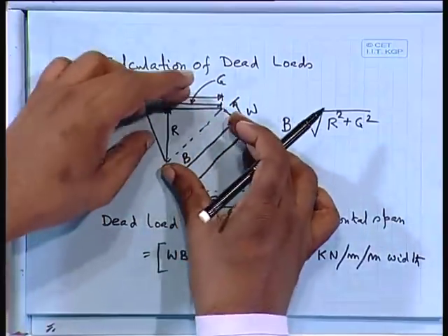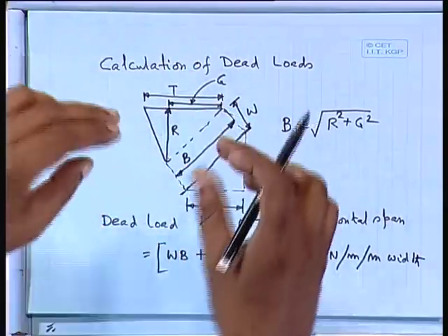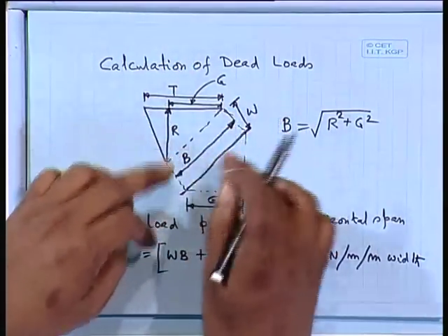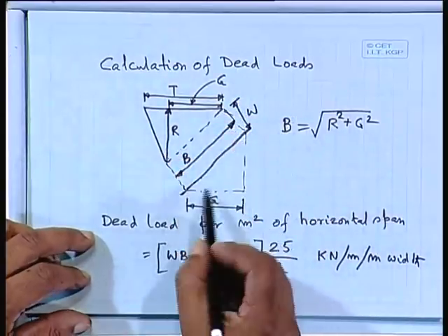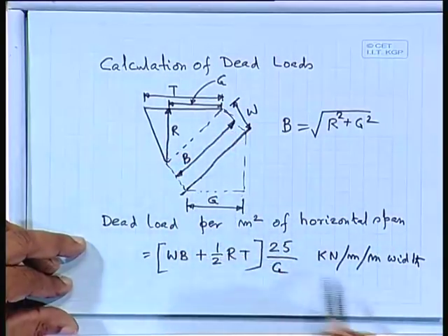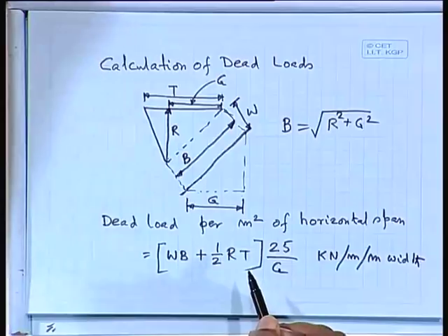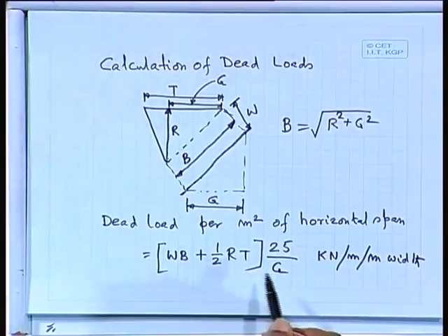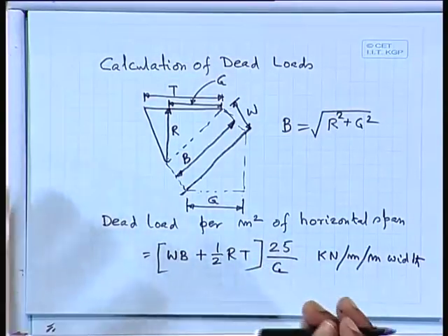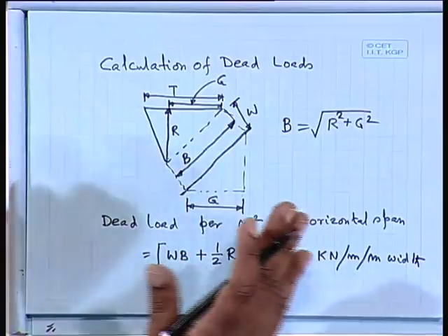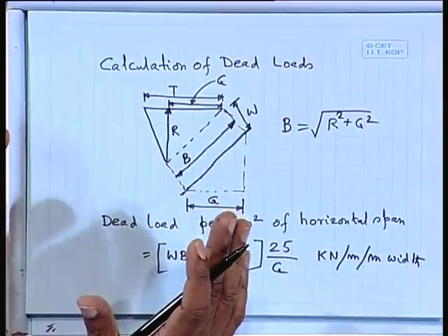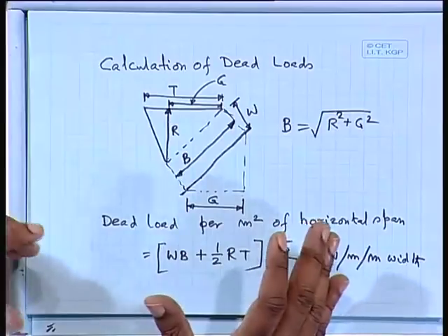So, I am taking 1 meter width, and we are having each step. So, each step we can take it. So, that means if you project it, it will go up. So, you will get something that in 3 dimension this is the unit one, and so I shall get per meter width, and this is the weight I can find out, that is the dead load you can get. So, in your whole design up to this only is different so far as the staircase is concerned, because if I can calculate the dead load, now we can consider it as, say, a slab or a beam.